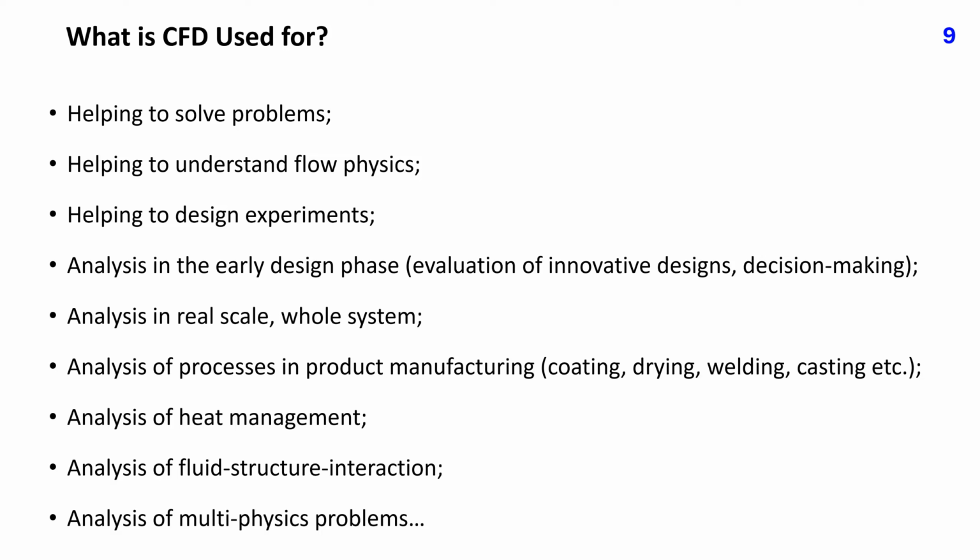CFD is especially useful in the analysis of heat management, cooling, heating, heat protection, etc. It is also used to simulate processes in product manufacturing like coating, drying, welding, casting, etc. Many multi-phase and multi-physics problems can also be simulated with a sufficient accuracy for practical applications like flows with free surfaces, cavitation, flow-induced motion of flying or floating bodies, flow-induced deformation of solid bodies, electrochemical effects like in batteries, or electromagnetic effects like in electromotors, and so on.